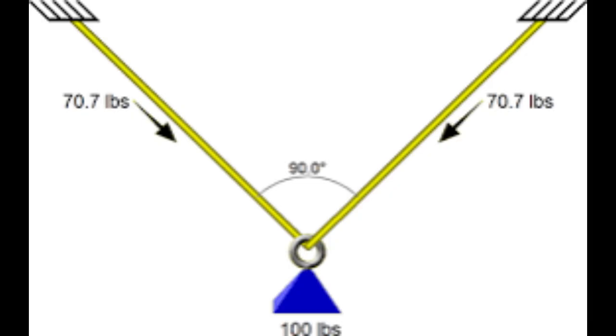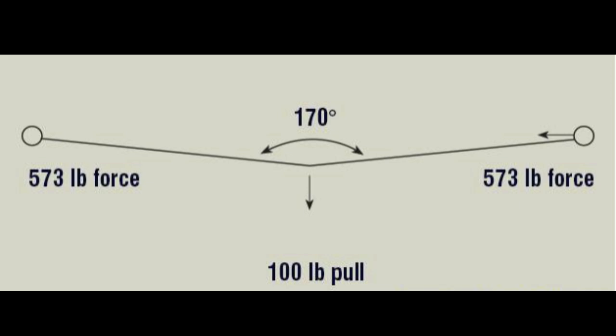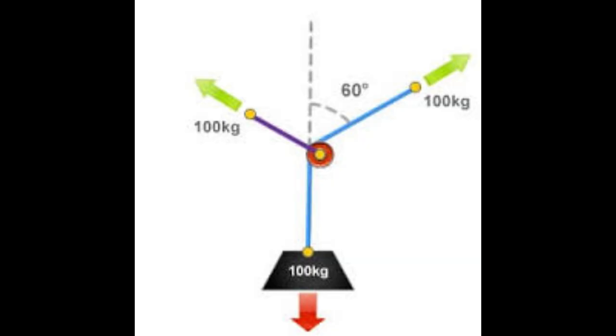Take a high line, for example. You've got a load moving across a chasm. 1. Gravity pulls it down, that's one vector. 2. The two anchors holding the line create vectors that oppose gravity and keep the load stable. 3. Then you add a haul line vector to actually move the load across. It's like invisible arrows pushing and pulling, all working together. And if you understand the vectors, you can predict how the system will behave, which makes everyone safer.